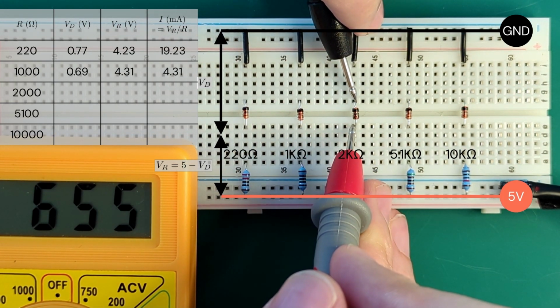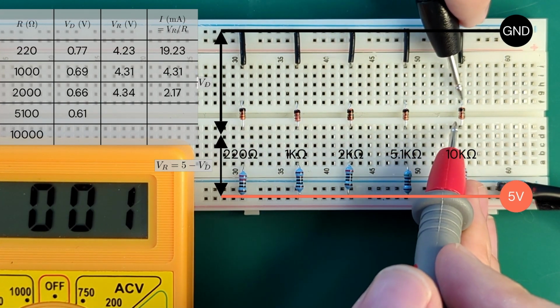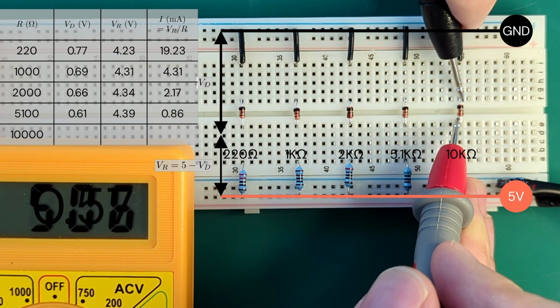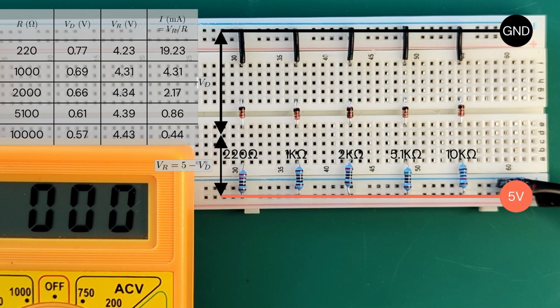Instead of using the diode equation that describes the plot, you can learn to eyeball it, which often is all you'll need. The first simplification is based on noting that the voltage doesn't change much for different currents in forward bias. So you can just take an average value and treat it as a constant, which for most silicon diodes like this is 0.7 volts.